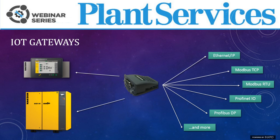Compressed air systems are quite often integrated to higher level controls or industrial automation systems or even building automation systems. And industrial gateways, as we can see here in the picture, enable a compressor to communicate via industrial protocol and can be the basis for an IoT solution as well. Nowadays, there are quite a number of IoT gateways available on the market. I'd just like to highlight here Ethernet IP and Modbus TCP, which are very common on the US market and in our industry as well.